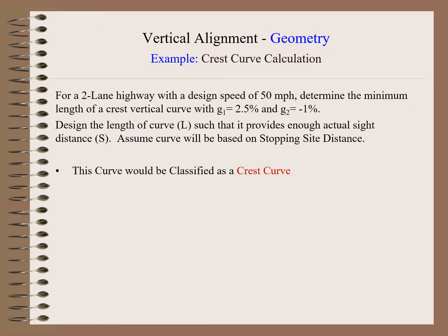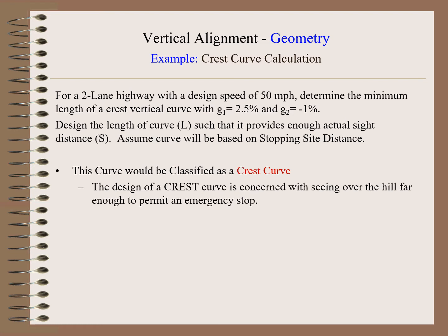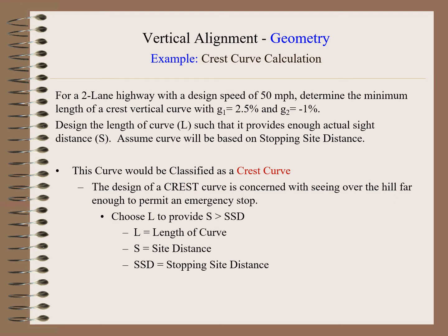So again, this curve would be classified as a crest curve based on the grades of the curve. The design of the crest curve is concerned with seeing over the hill far enough to permit an emergency stop. Choose L to provide S sight distance, S greater than the stopping sight distance. L equals length of curve, S equals sight distance, and SSD equals stopping sight distance.